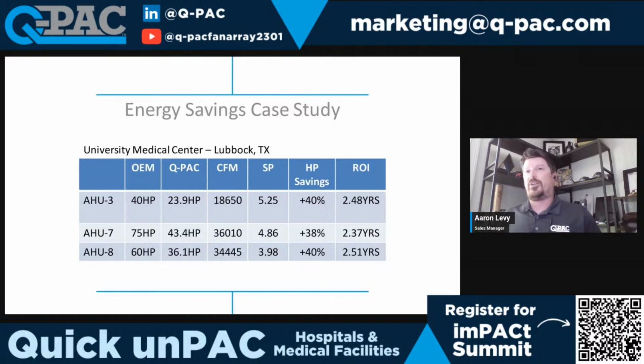So in a lot of ways, you can double your efficiency just by going to EC. And so that pays back in kilowatt power and horsepower. That's why you'll very rarely see a lot of these EC fans are somewhere between 5 horsepower and 10. We just use multiples of those to achieve what we need.